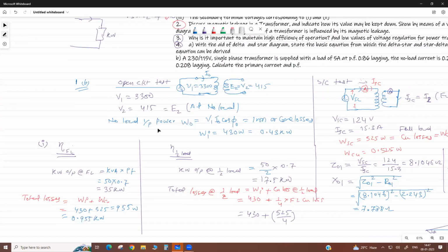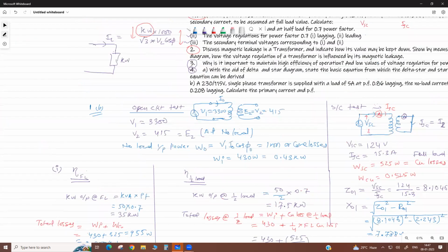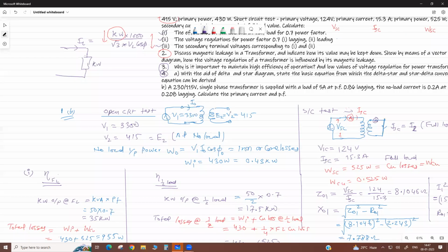Yes. Suppose we talk about when at no load. At no load, why do we neglect the copper loss? Because there is no power output. Generally, very little current is taken. Correct? So this total power input is taken as core losses because it is utilized in magnetization only.